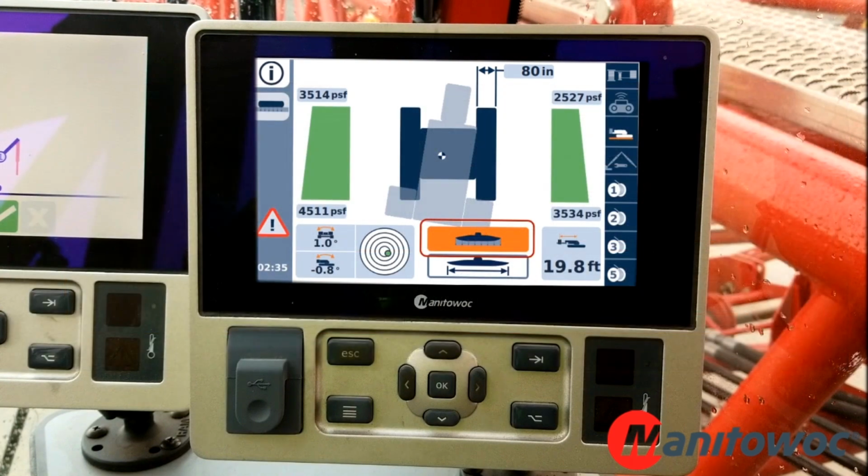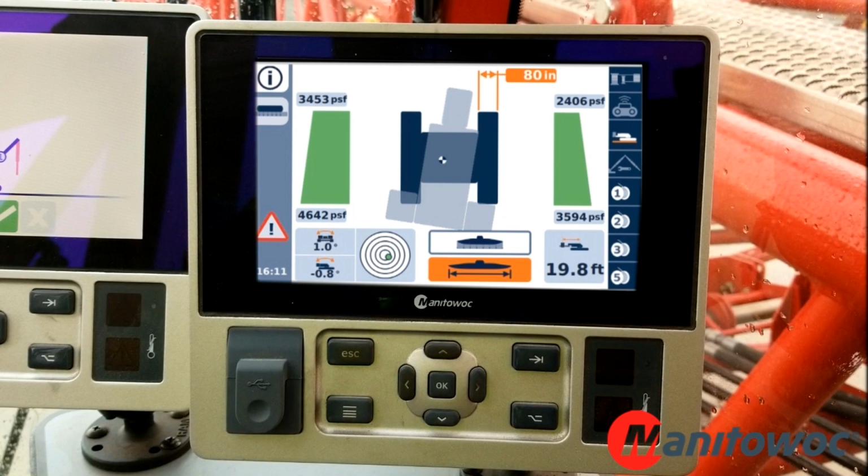When selecting the pad width, a passcode is required. Passcode entry boxes shown require the passcode 2401 and must be entered into the crane display to change the pad width. Use the jog dial or scroll keys to highlight the pad width section of the screen. Press the OK key. Passcode boxes will appear with up and down arrows by the first digit.